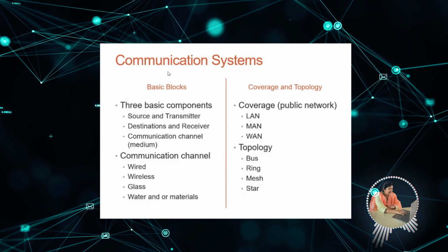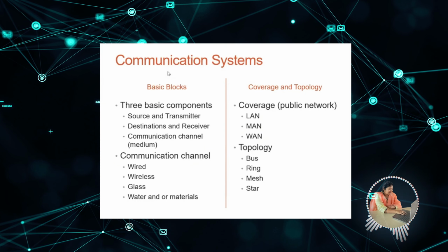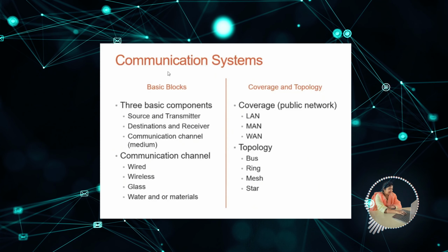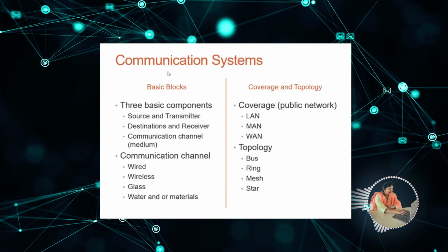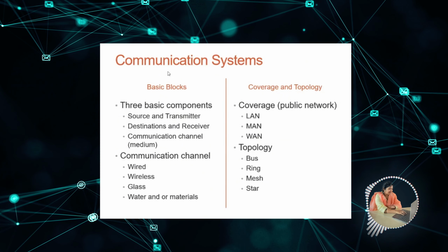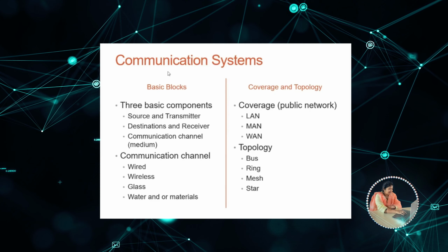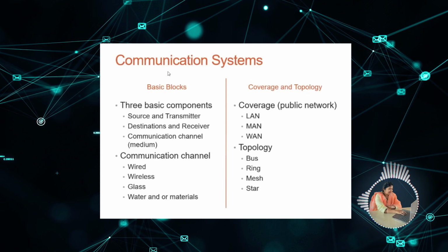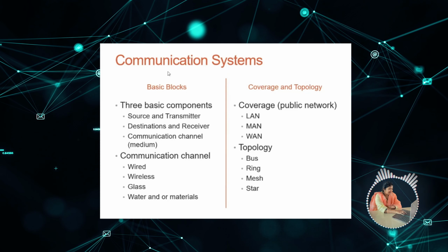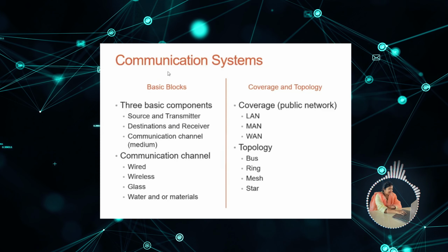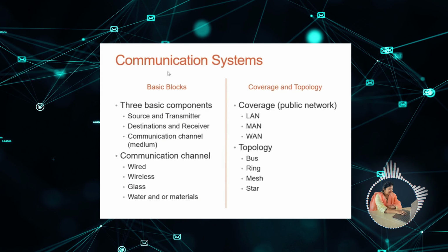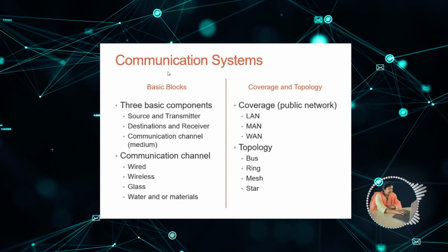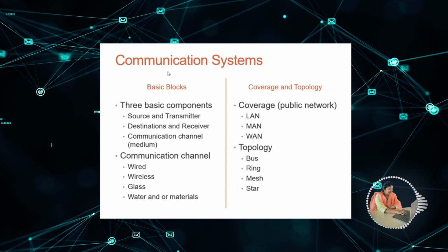Source and transmitter, why are both different? Because the transmitter has encoding components, and everything required to convert an analog signal into digital if we are performing digital transmission, and the source is going to transmit a signal in a particular electrical form. Because on the transmission line, what we are transmitting is 0 and 1. So 1 has one voltage level and 0 has another voltage level.